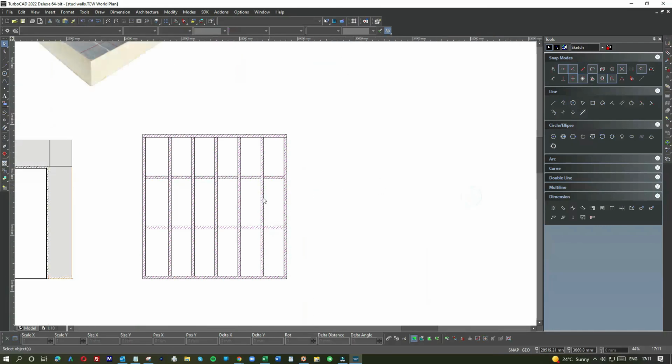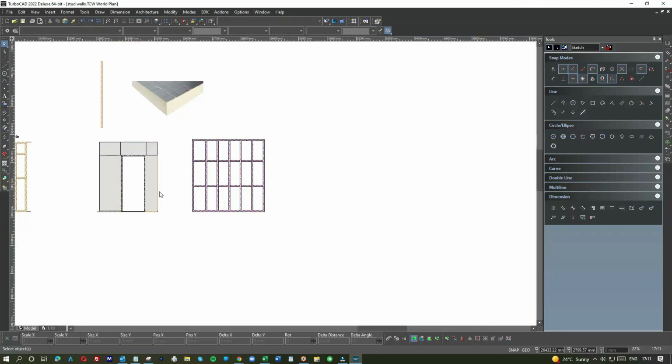These are the noggins, and the positioning is determined by the plasterboard you're going to use, be it 6x3, 8x4, that sort of thing. And if there's no one there to tell you, then you make a decision. It's nice to get it spaced out properly. So I wouldn't have done 4s on this, because a 6x3 900 high would have been more sturdy. When you do put the plasterboard on, stagger it.